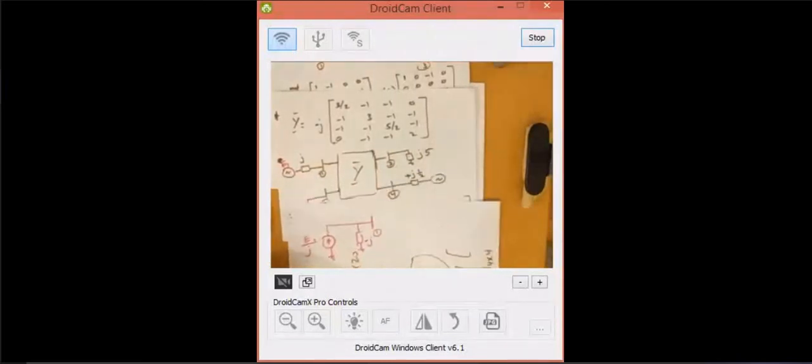So in bus number 1, when we want to calculate Y or Z, it is the same as the Thevenin equivalent. In the Thevenin equivalent circuit, a voltage source is replaced by a short circuit, and a current source is removed and replaced with an open circuit.